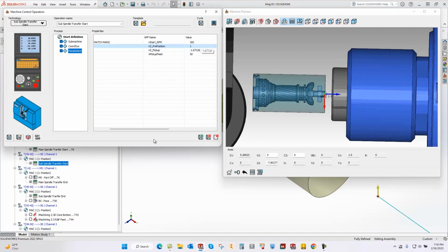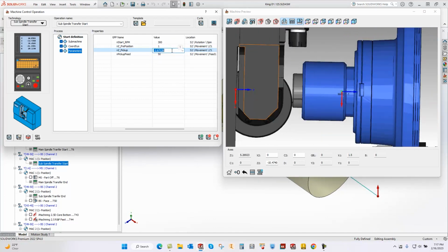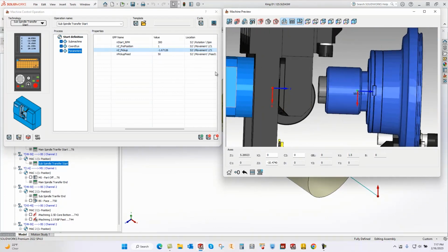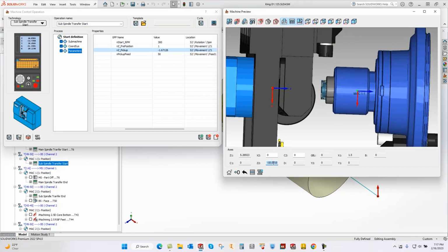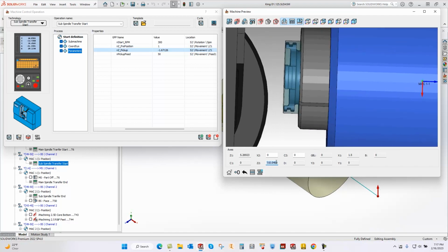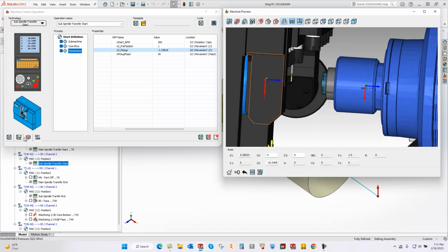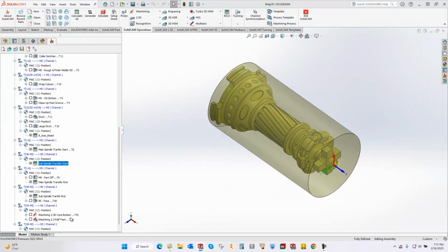And then the pickup location where we're going to actually clamp. Now, this is where I could pull up, sorry, let me scroll this over a little bit and pick up a setup location. Or you can simply pick here and move the part onto where you want it to be. And that's going to be your Z2 again. I'm too far. Let's go up to here, about somewhere in this neighborhood, and we'll go ahead and paste that value in as well. So that is how you set up your positioning of grabbing the part, and you hit save and calculate, and you're set and you're good to go.